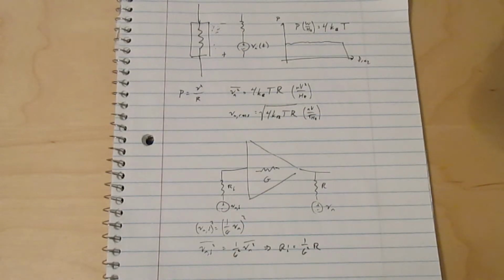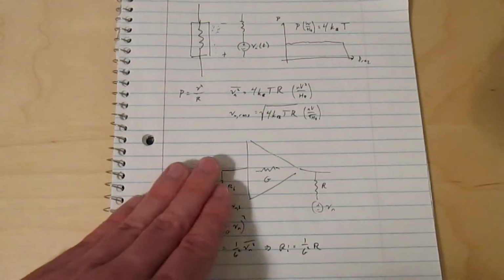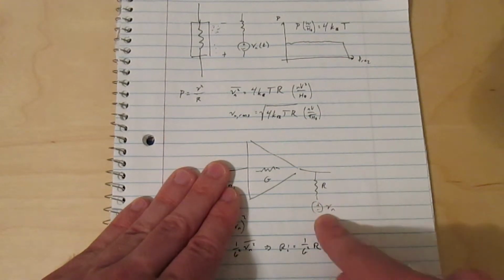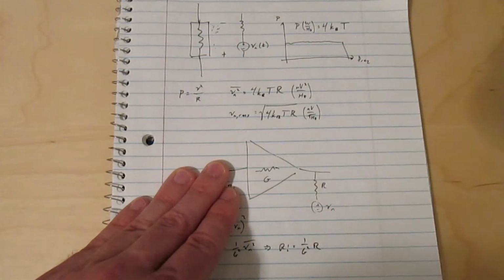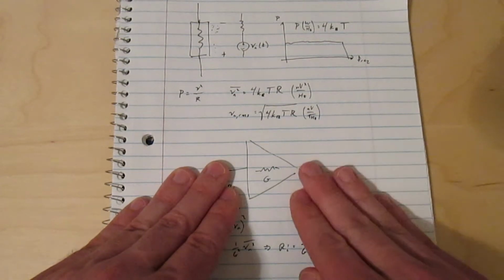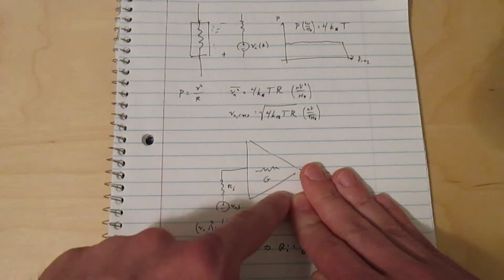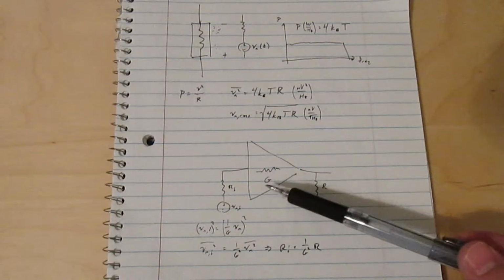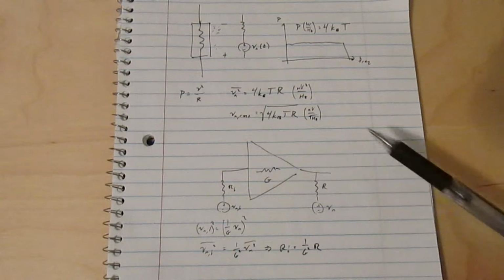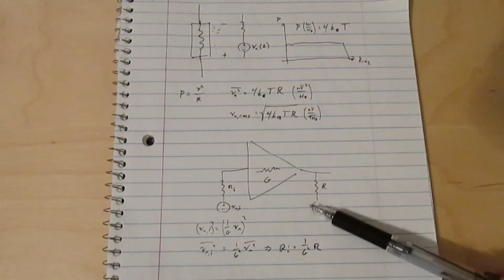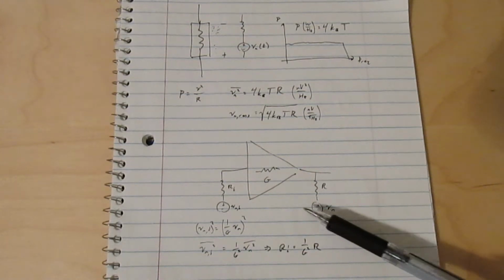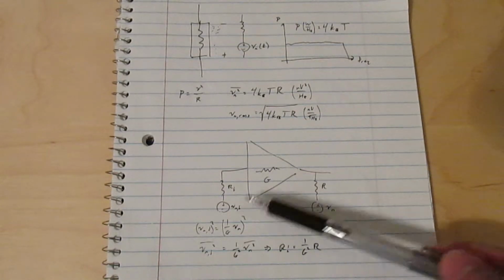And really the only important case we need to worry about for this video is having a noisy resistor at the output of an amplifier. And what we need to figure out is how big of a noisy resistor would it take at the input to give us the same amount of output noise. So we can start by saying the amplifier has a voltage gain of G, and then we can relate the output noise voltage back to the input by dividing it by the gain.